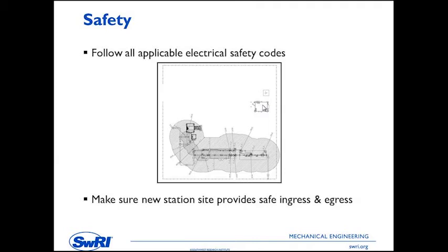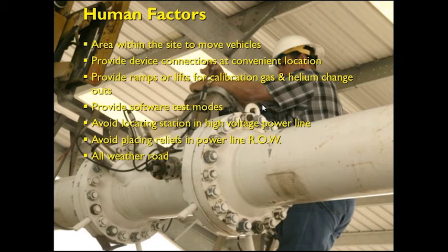There are many different interpretations of how that is done, though, and each company has their own standard that they apply. Some companies have a single room installation where the chromatograph and controller and flow computer are all in the same room. They say it's unclassified, therefore we don't have to do anything with that.